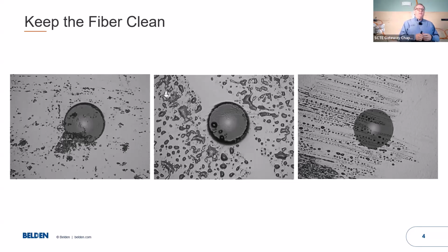There's a lot of habit of just taking out new jumpers, getting a new drop, running it through, and just plugging it into the house box or into the equipment. Always have to clean fiber, especially when it's out of the bag. It should be scoped. I know sometimes there are equipment differences depending on whether or not you have them. You should always pay attention and clean them.